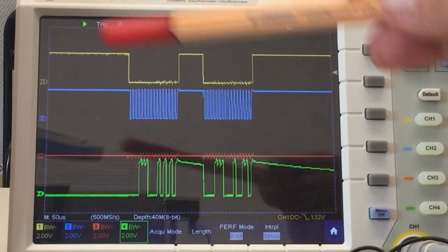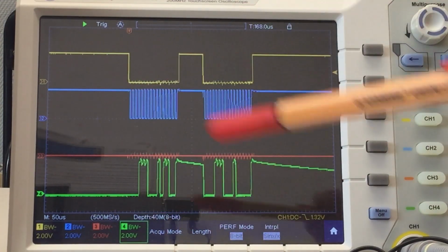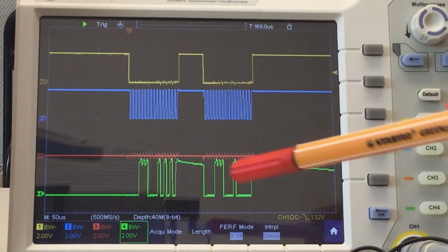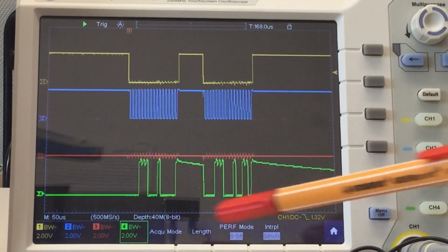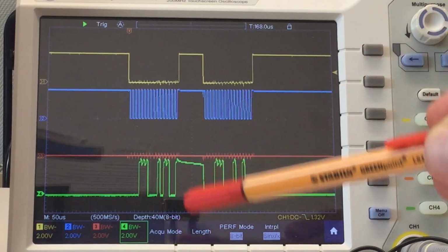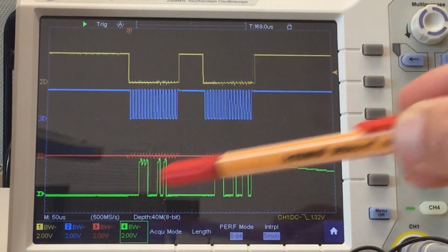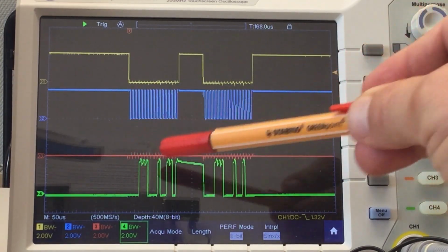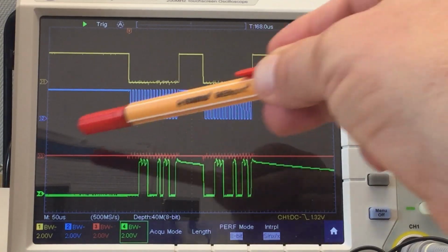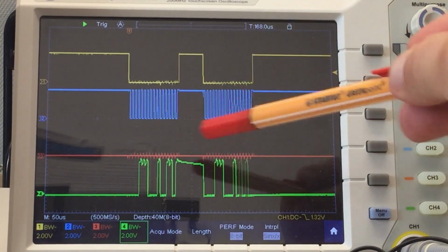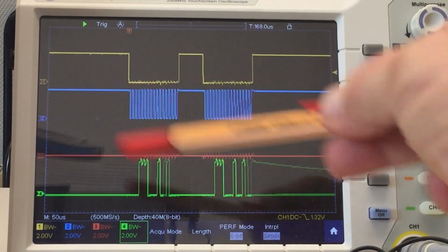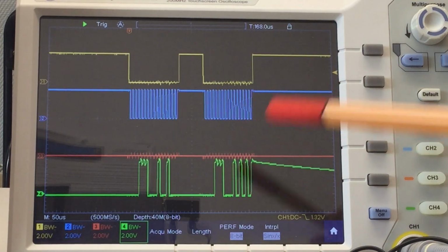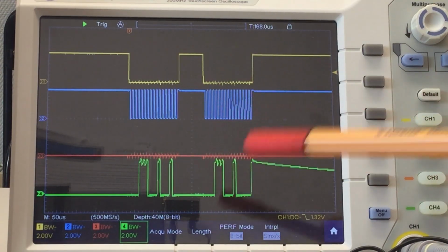So the read register in the software always sends a command, and then in a second SPI transaction it reads the returned data. So this is the returned data for this command here. Incidentally, I'm only sending here read angle register commands, 16 times 0. So yeah, there's room for optimization here, but I also talked about that in the code review walkthrough in the second part.